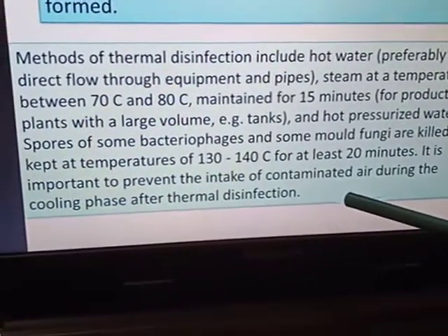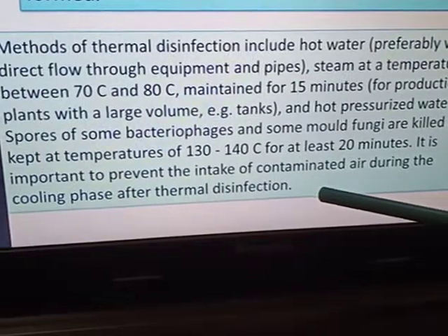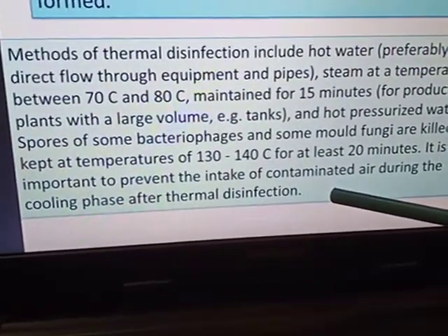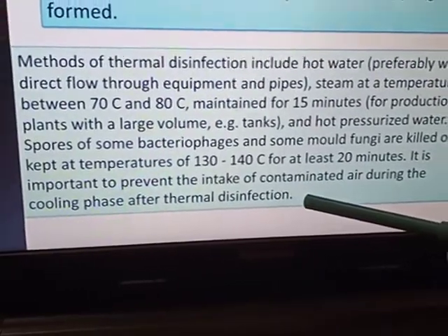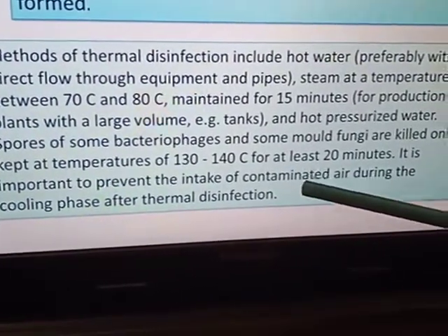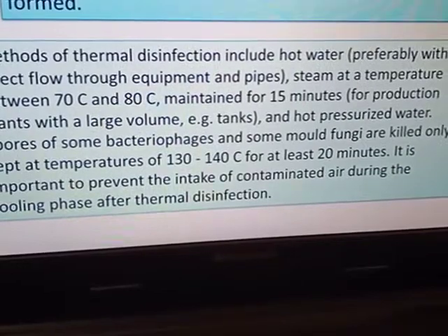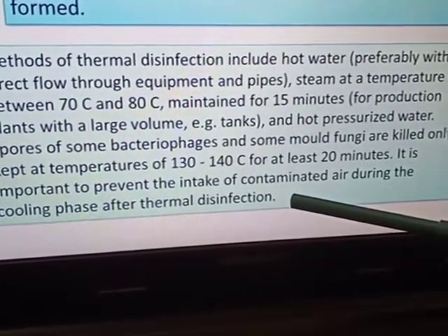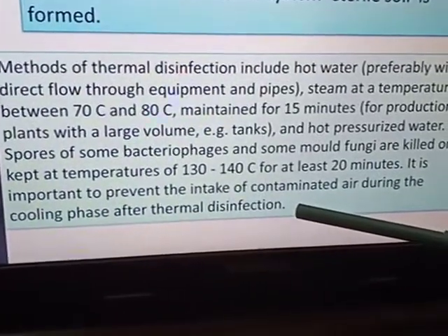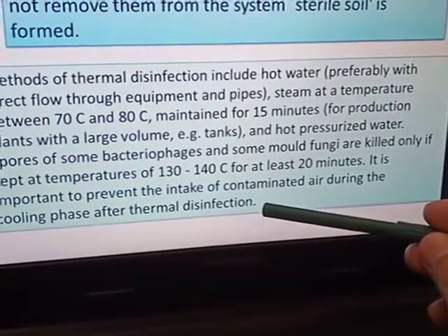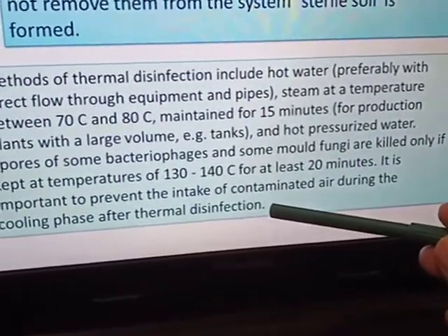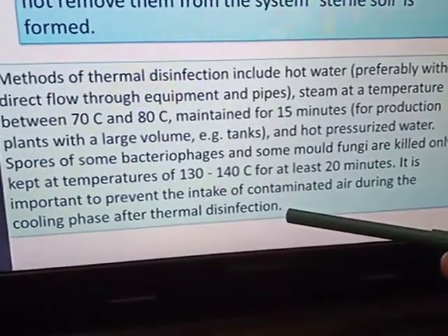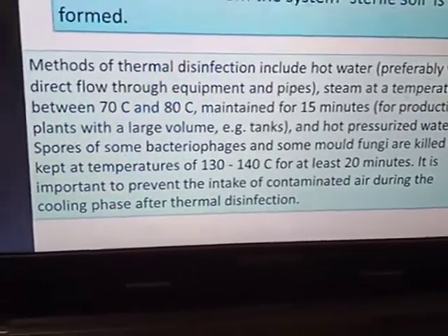for at least 20 minutes. It is important to prevent the intake of contaminated air during the cooling phase after thermal disinfection. You must avoid external air entering the equipment, or if it needs to enter so that the pressure is kept at a safe level, then you have to filter the air so that bacteria will not enter the equipment.